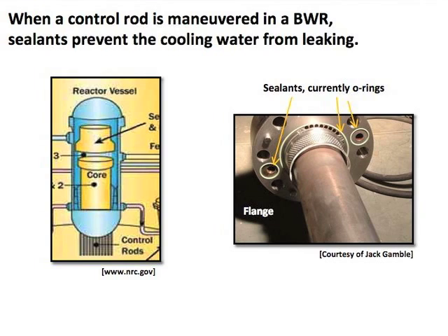The O-rings, as you can see, are labeled by the yellow arrows. They prevent the cooling water from leaking out of the control rod. There are 3 O-rings, 1 large one in the center and 2 smaller ones on the outside. Now, the O-rings are Teflon-coated hollow stainless steel tubes. And depending on their size, whether they are the large ones or the smaller ones, either have 4 pinholes or 2 pinholes, respectively.